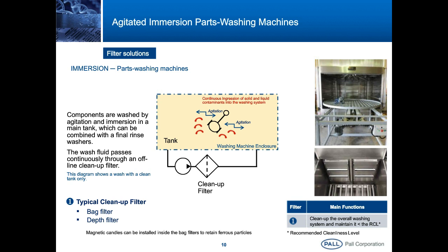Here, the filter rating depends on the cleanness level to reach and maintain over time. This is what we call the RCL, for recommended cleanness level. It always depends on the component cleanness code to meet. Usually, it is defined by the manufacturer or the tier supplier.